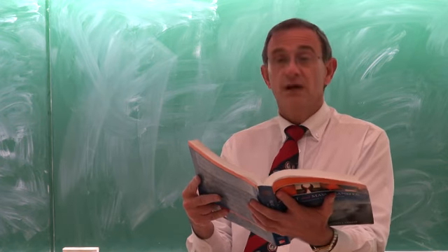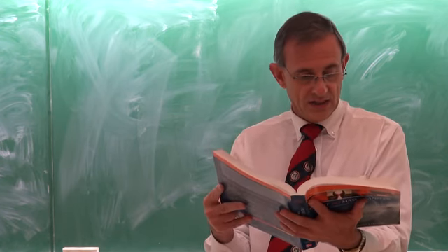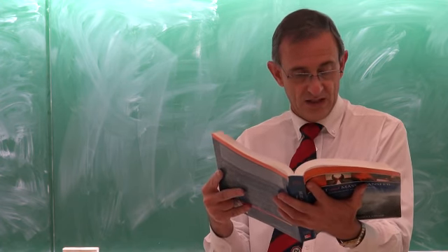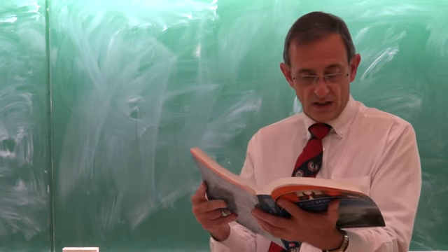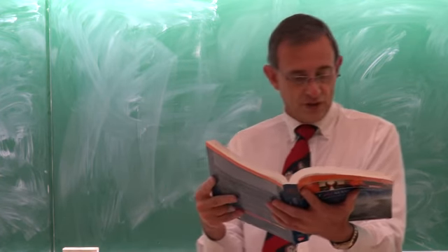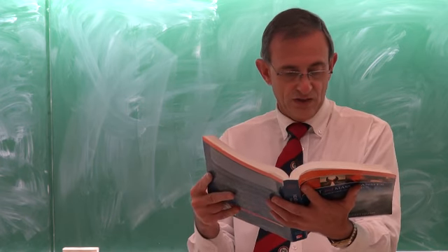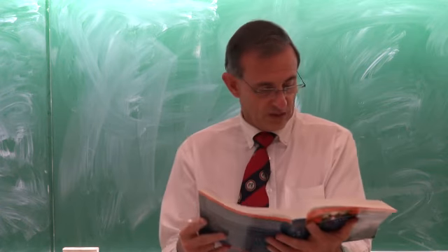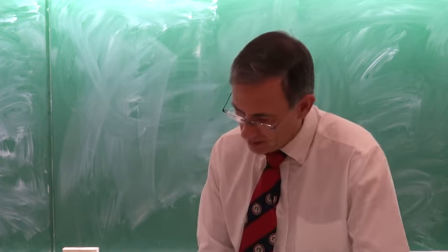It passes through the attic space of a house. Hot air enters the duct at 1 atmosphere and 80 degrees Celsius at a volume flow rate of 0.15 cubic meters per second. The duct surface is nearly isothermal at 60 degrees Celsius. Isothermal means constant temperature. Determine the rate of heat loss from the duct to the attic space and the pressure difference between the inlet and outlet sections of the duct. Right, so the problem has already been summarized here on the board.